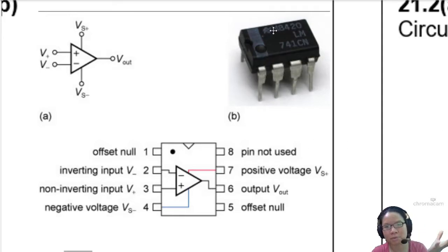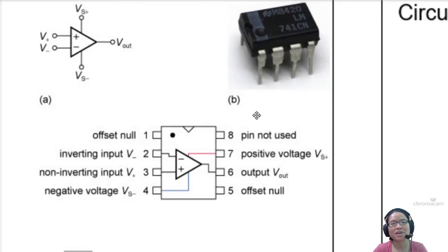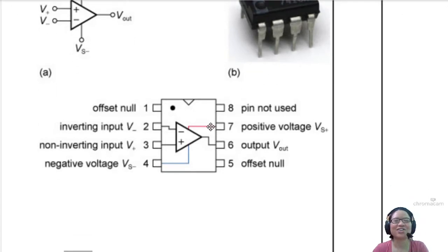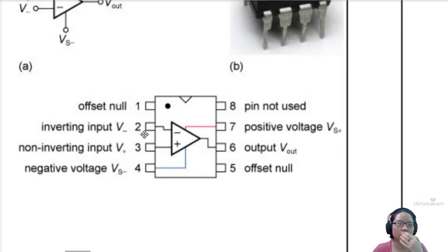So this is how your op-amp looks, right? The general op-amp that we will use has the 741 code, and you can see that it has 4 legs on each side, 4 connectors. You can connect this normally to a breadboard, not through your crocodile clamps anymore, because we have levelled up. And of course, this one looks a bit confusing, right? Because you have certain pins that you don't use, and certain pins are just there to reset the op-amp, which we call offset null.